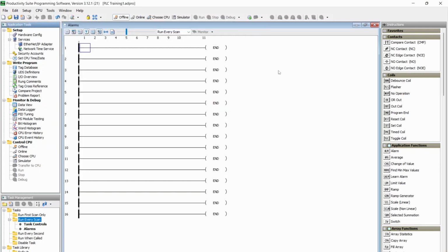So I'm going to close out the hardware now. Now here's our ladder diagram for our tank controls. Let's go ahead and make sure that we're on tank control. So I'm going to double click here. Okay. So right up here it tells us we're in our tank controls. So what's the first thing I said was going to happen? The first thing that I said was going to happen was that our float switch was going to engage. But before that even happens, we need to make sure that our start run is in the run position.